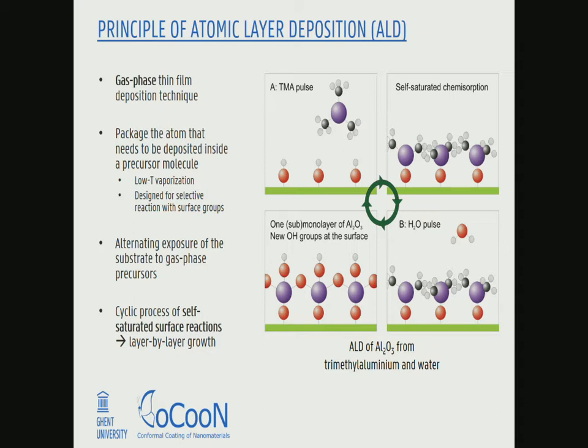In this case, since you're aiming for an aluminum oxide film, basically junk, contaminants left behind. And therefore, in this step in ALD, you pump away or flush out whatever precursor vapor is still in your chamber. You leave your surface in this condition, and you admit in a second step, and therefore it's alternating exposure of the surface to different gases.